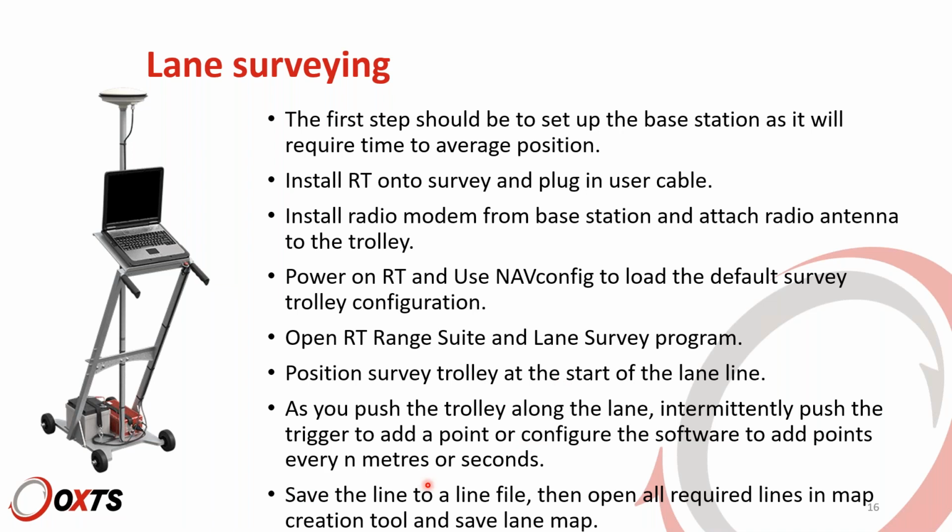We'll generally say for a nice straight line, unless it's been badly painted and is quite wiggly, assuming it's a well-painted straight line, you probably only need points a handful of meters apart. That will give you a nice, smooth, solid line that isn't too noisy.